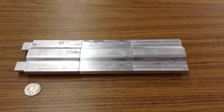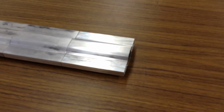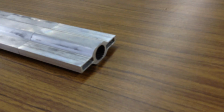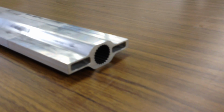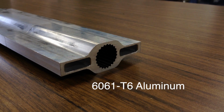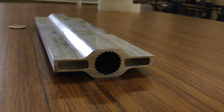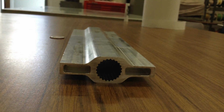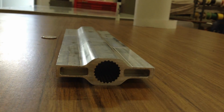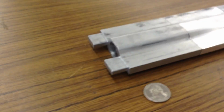Here's a closer look at the gust vane spars with a quarter for reference. As you can see, the spars are made of machined sections of metal. On one end of each spar piece is a splined broach to accept the drive shaft, as well as 2 grooves to accept the previous spar's tongue extensions.